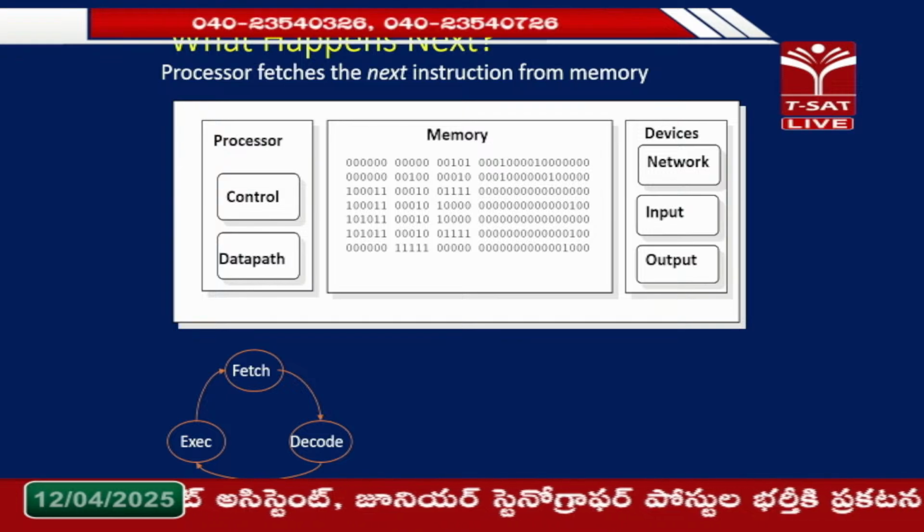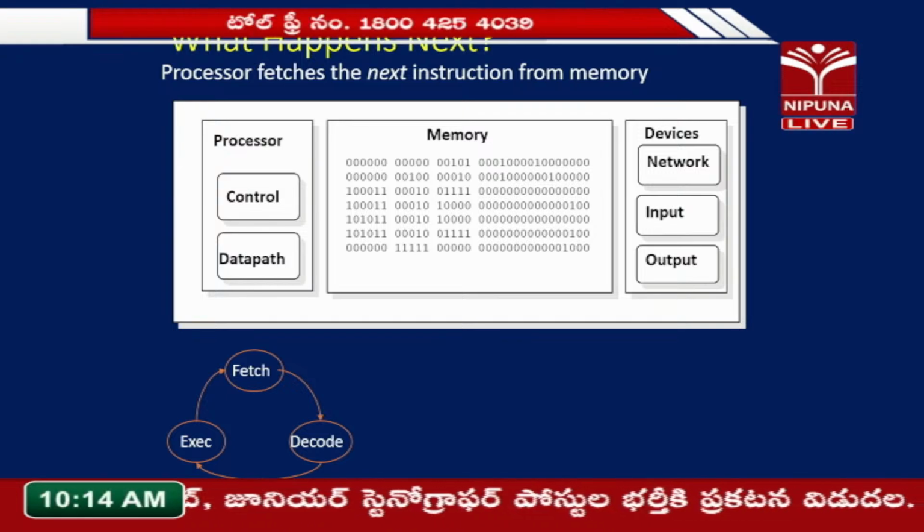So, all of these basically mean that you are fetching the instruction that is coming along. It could be the instruction after the current instruction, because it is a sequential instruction, or if it is a branch instruction, you need to go and fetch the branch target instruction, which could be the next one or a later one. Okay.